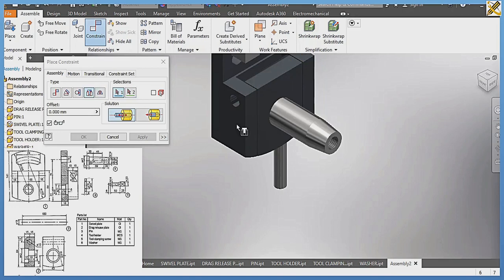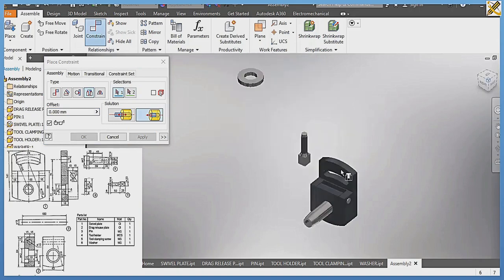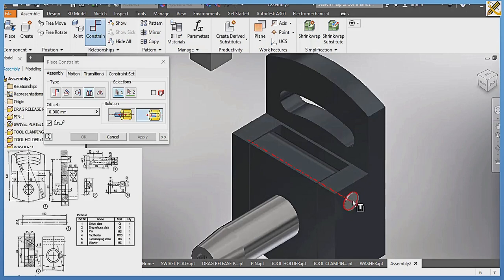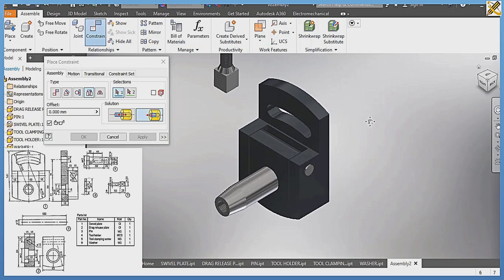Alright, so the next is this pin, insert, placing this right here and insert. This pin is also 100 mm, while the distance in between is 97, so minus 1.5. Yeah, you can see what I'm trying to explain. It comes out here a little, and look at this also, it comes out here a little also. Alright, so that being settled, the next thing is